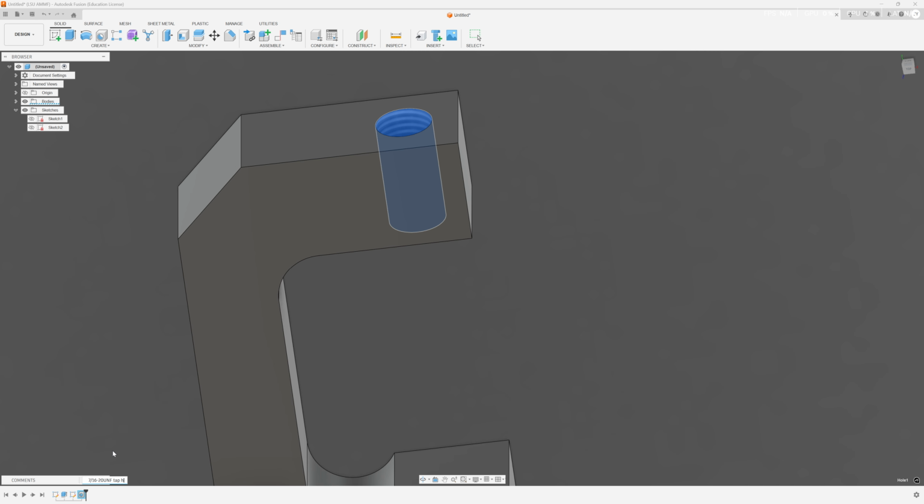Tap hole. Enter. By naming it 7/16-20, when I look through this print and select that hole and it highlights it for me, I know exactly what type of tap I'm supposed to be going back into that hole with.